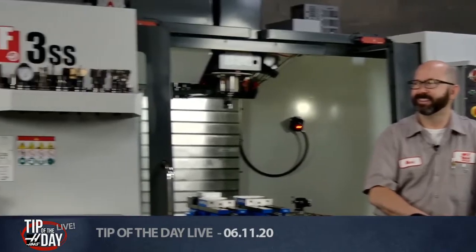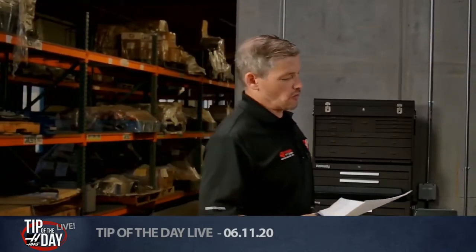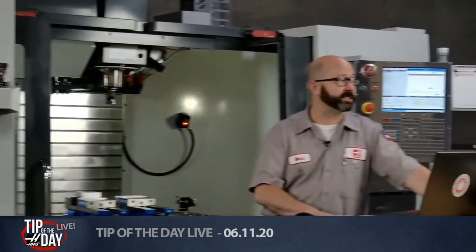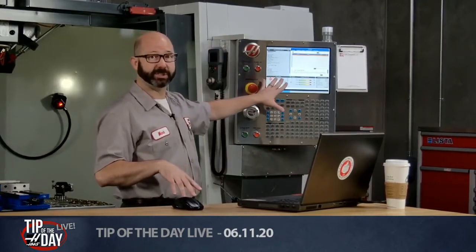Okay, let's go back to one from previous weeks. Jake Cartwright 1992 says, is there an M code to override rapids on an ST15? An M code to override rapids on an ST15. I got an ST20 here. There's not an M code, but there are ways to adjust your rapid overrides. And this kind of comes back to the same thing. Settings on a machine, mill or lathe.